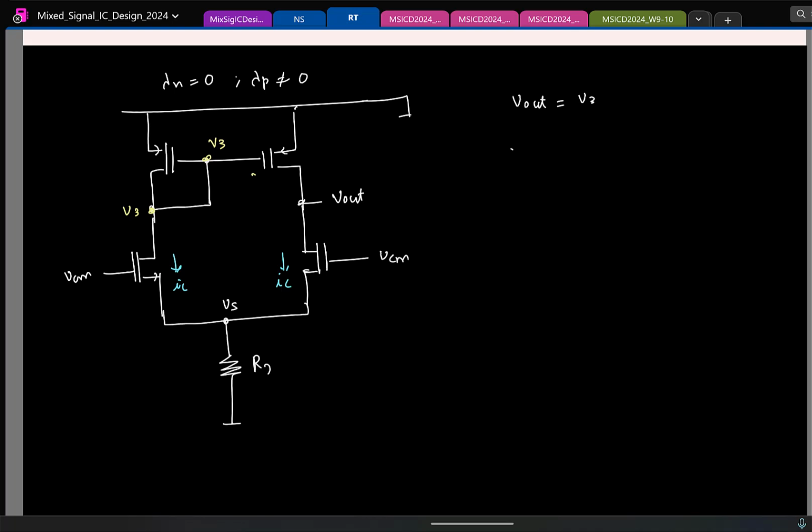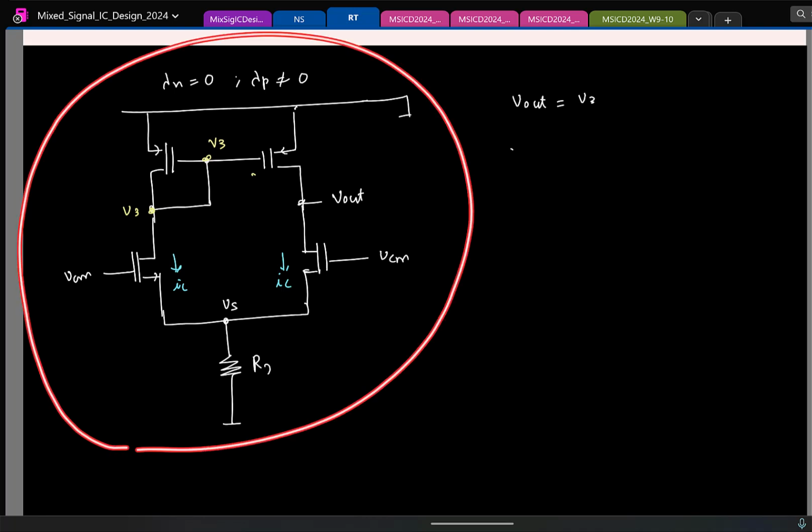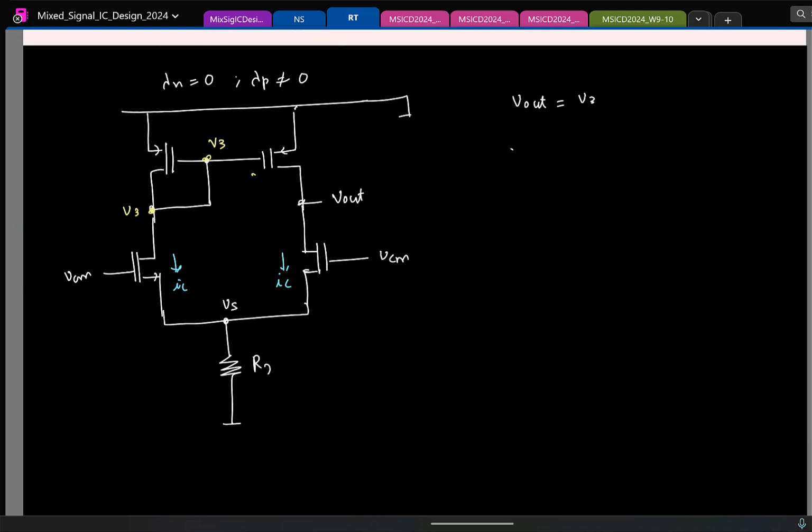We didn't change anything, right? The same circuit. What happened to the input? Yes, as long as you feed in a common mode excitation, both these nodes will be at the same voltage. So this is another condition wherein, as long as you have a common mode excitation, the actual circuit, which was asymmetric to start with, starts to behave like a symmetric circuit.